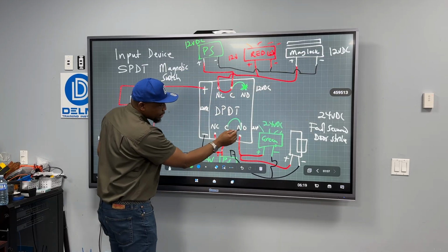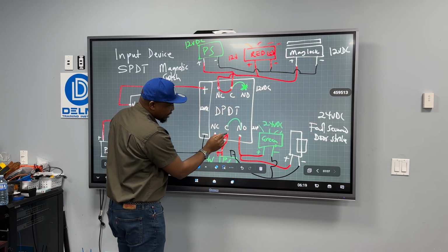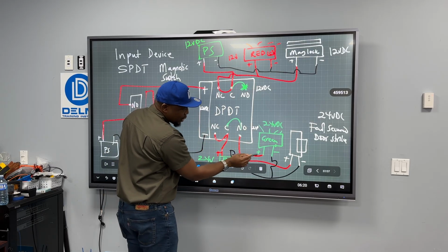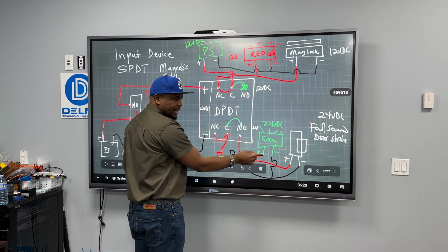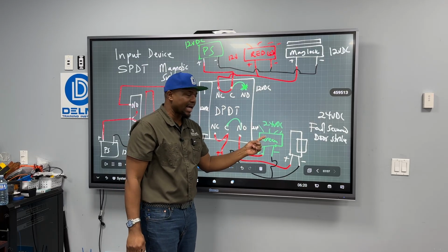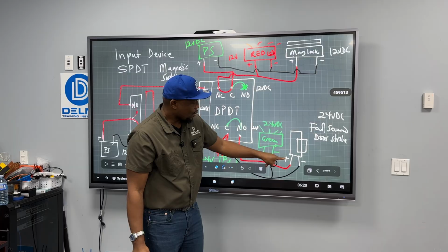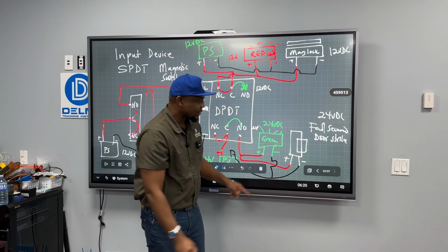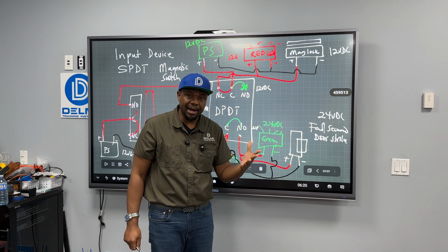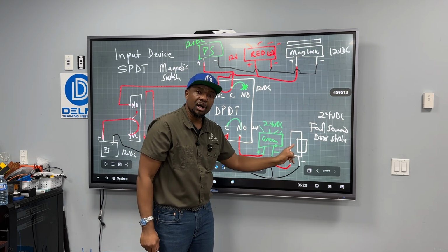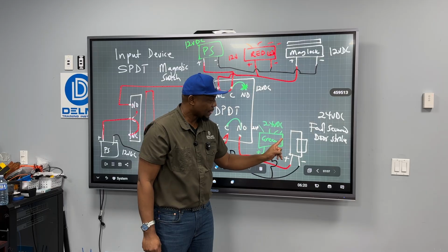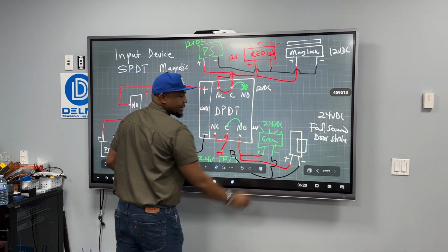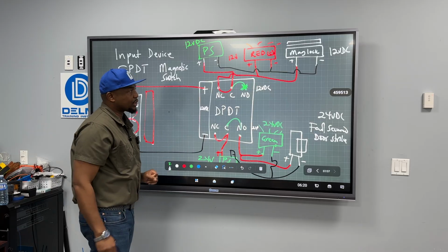Now let's look here. The voltage is now here. So the 24 volts goes from here. Look what is getting power, the positive terminal here. So what is going to happen to the green LED? It's going to turn on. What is going to happen to this? Because the positive comes here again. Now this door strike is getting power. And as a result, it unlocks. Right? So that's going to unlock when I bring that close by. And that's just pretty much what is going to happen.